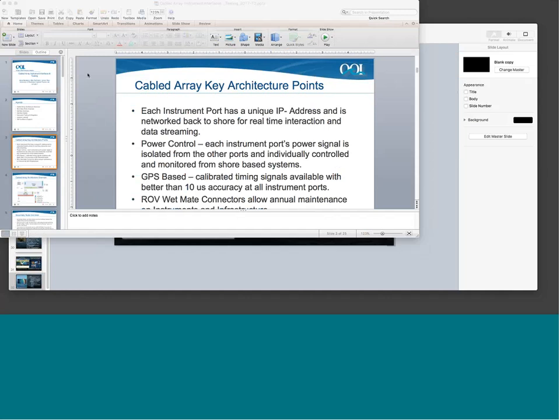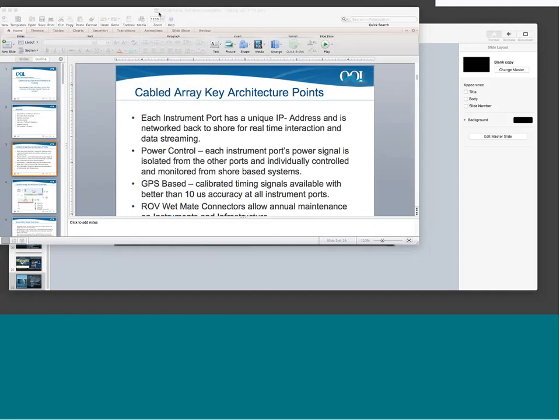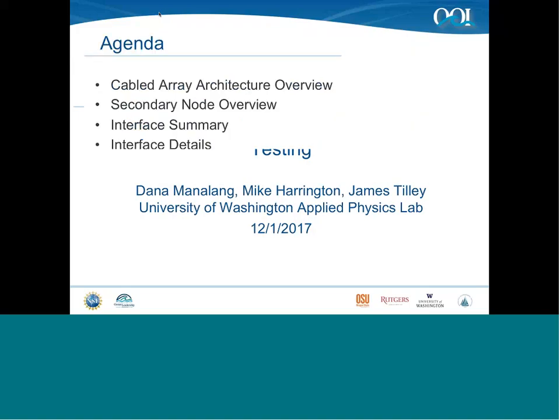We can control power instrument by instrument from shore. We collect and monitor the data for each instrument port, including things like electrical current, voltage, and whether there's ground fault issues on that port.